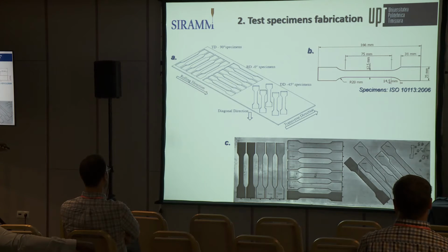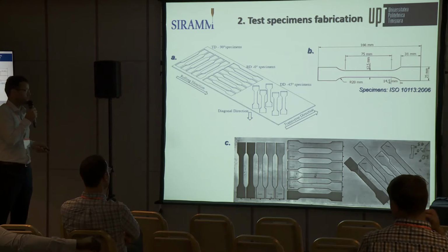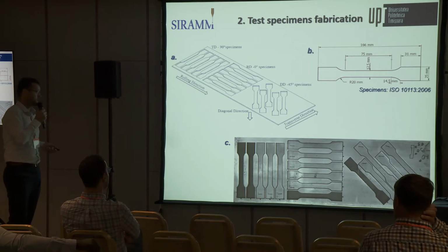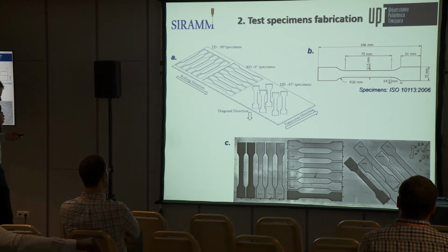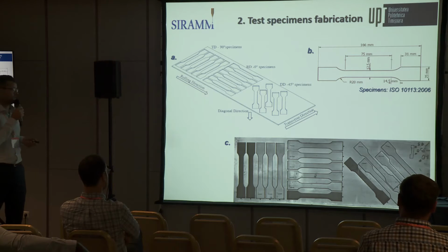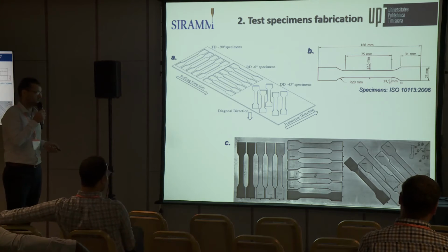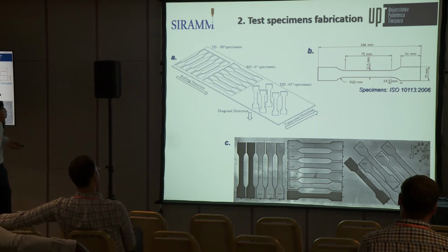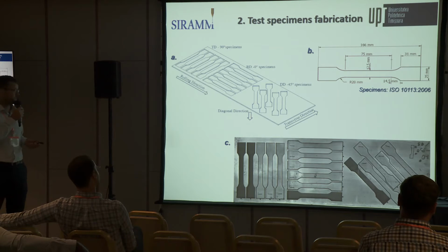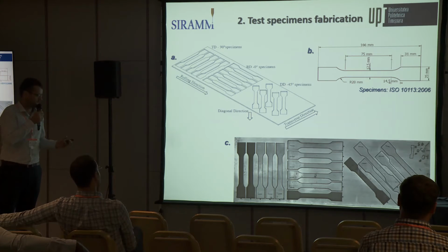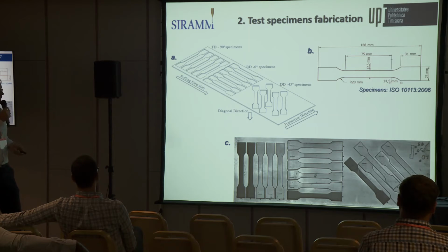We use the test specimen according to ISO 10130, with a thickness of 3 millimeters, a width of 12.5 millimeters, and a gauge length of about 75 millimeters.